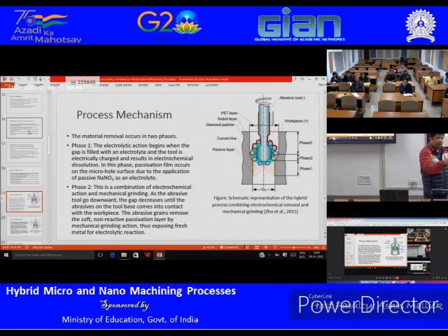Now, why does it continue? One thing you need to make sure of is that above the grinding wheel you have some conductive metals, right? Although you reduce the diameter to increase the gap, this is not electrical discharge. This is electrochemical dissolution, so it will still take place. How can you avoid that? You make sure that none of the conductive layer is exposed after machining is happening. On all the tool shank, you just use some kind of coating to avoid the electrochemical dissolution.